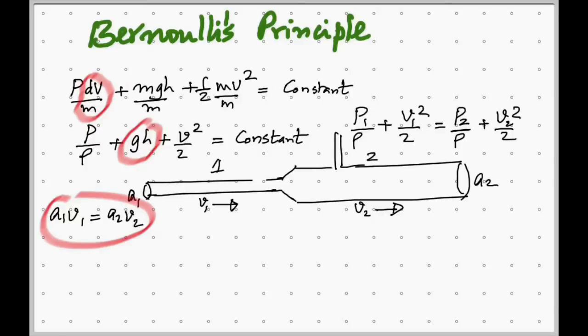So if you have two vertical tubes here, as the liquid flows, it will rise up in those vertical tubes, right? And both are open to the atmosphere. I mean, there's enough height so the liquid doesn't spray out. Are you with me? So when the liquid rises, where will it rise up more? Where is the pressure greater? Pressure is greater at P2. So surely it'll rise up more here, and here maybe something till here.